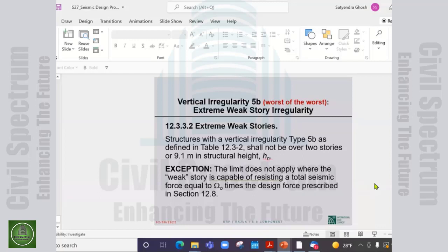I kept on saying, I don't know how many times, that gravity loads do not cause any appreciable lateral drift, unless you have a very significant lack of symmetry. So for the vast majority of buildings, it simply does not matter how much gravity load you have sitting on your structure when you calculate your drift.